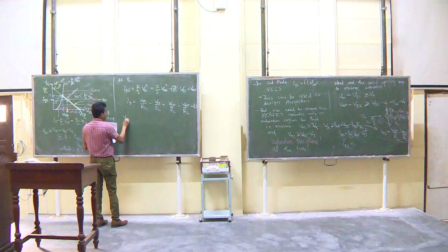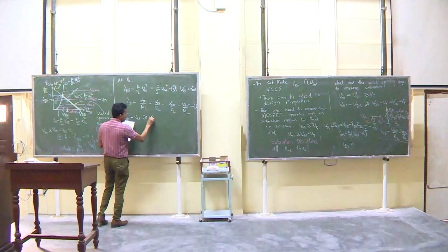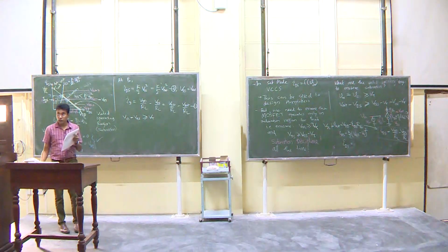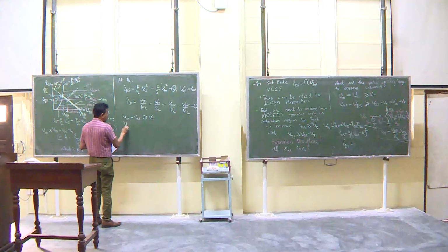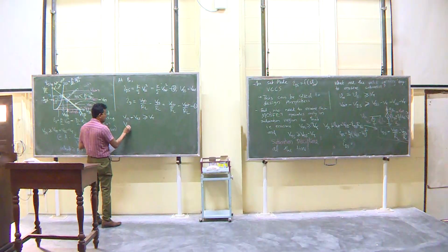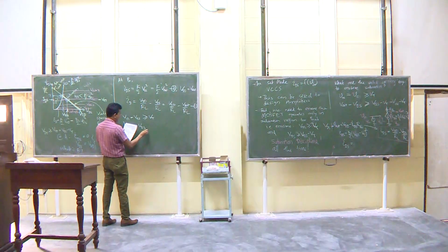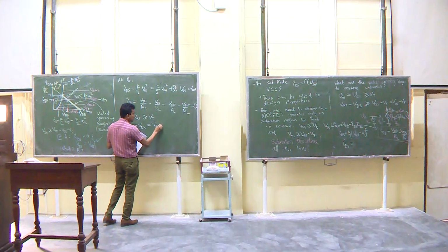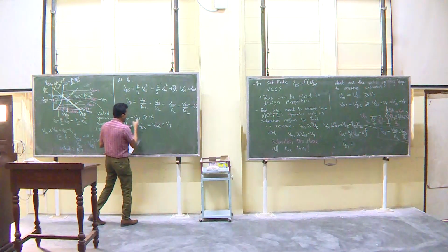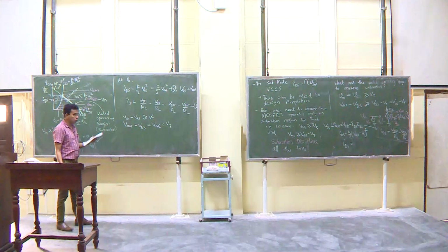But what is V in? V in is equal to VGS, and we know this should be greater than or equal to threshold voltage, otherwise this will not be in the on state, right. So this is something there, and we have to know this is in the saturation region. So therefore, V out, VDS has to be equal to VGS minus VT. Remember earlier we had greater than, now we have equal, right.